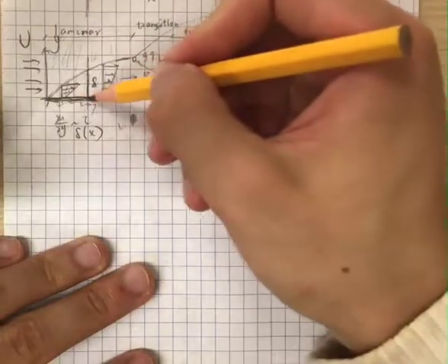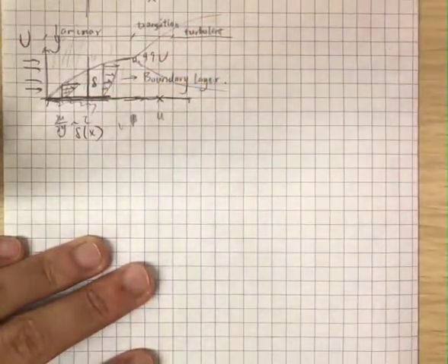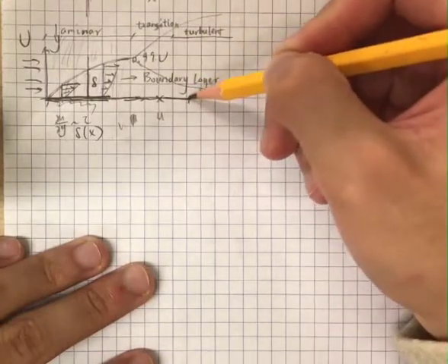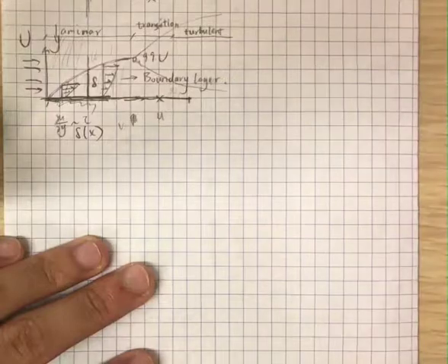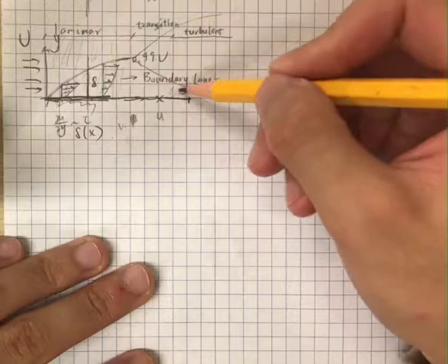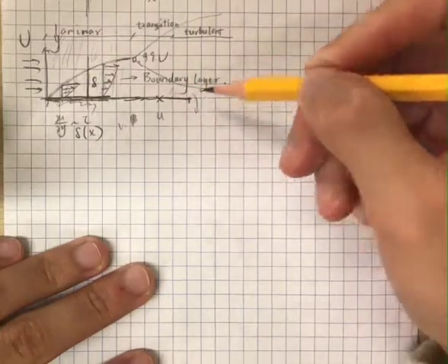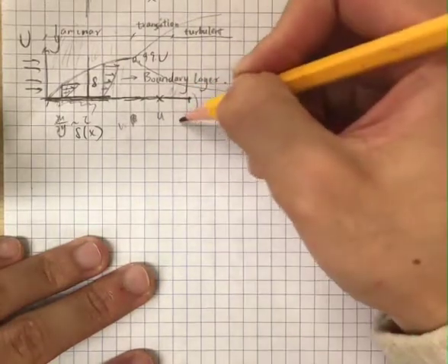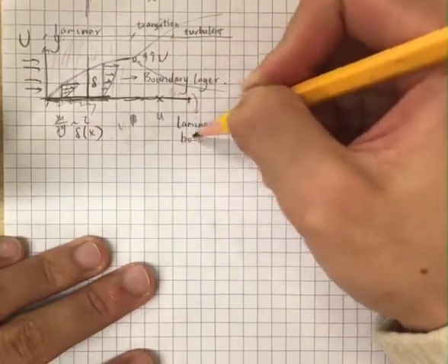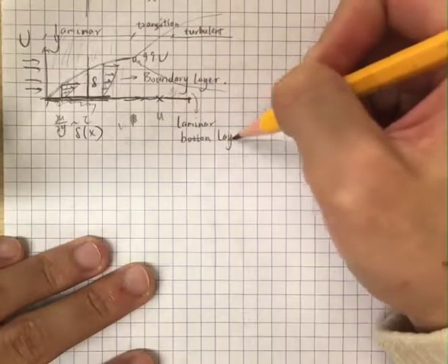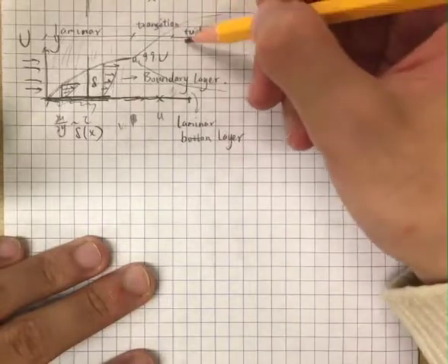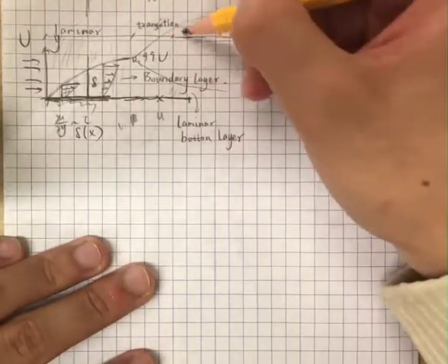But if our plate has a certain length, then down here, the fluid that is very near our boundary, the tau will still be big. So here, we would expect to see a laminar bottom layer. If we draw the velocity profile, the velocity at the turbulent region may look like this.